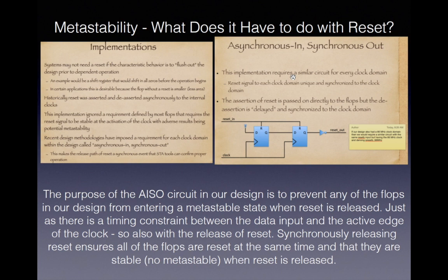You are cheating yourself if you don't take the time to understand not only how we define the circuit in Verilog and how it will be implemented in hardware, but why we're implementing it. That would be a good education. And the last note here: keep in mind, if you have a design that has multiple clock domains, you must have a circuit like this for each clock domain.